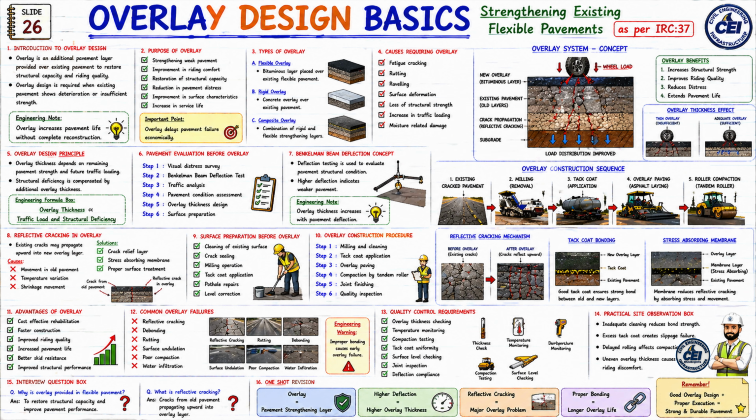Now let us look at the sixth topic. Pavement evaluation before overlay. Pavement evaluation is very important before designing an overlay. Step 1. Visual distress survey. Step 2. Benkelman beam deflection test. Step 3. Traffic analysis. Step 4. Pavement condition assessment. Step 5. Overlay thickness design. Step 6. Surface preparation. And without proper evaluation, the overlay is not successful.